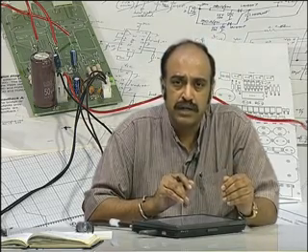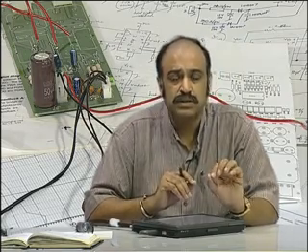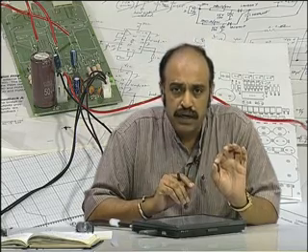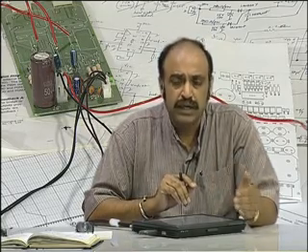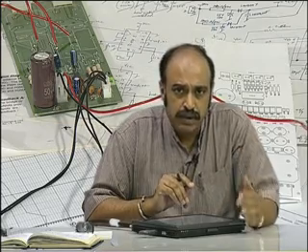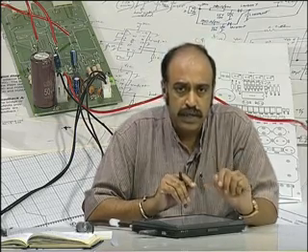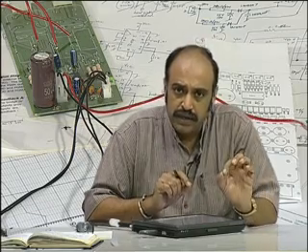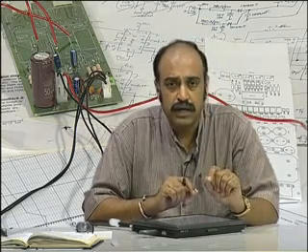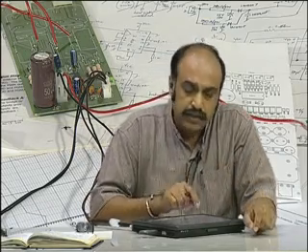When you restrict to electric circuits, if it is an inductor, the inductor current is a state variable, and if it is the capacitance, the voltage across the capacitance is a state variable. After having identified all the inductor currents and the state variables, mark them on the circuit.